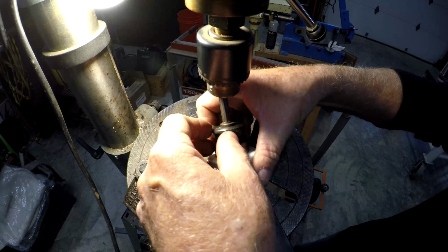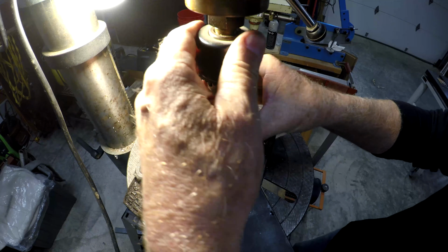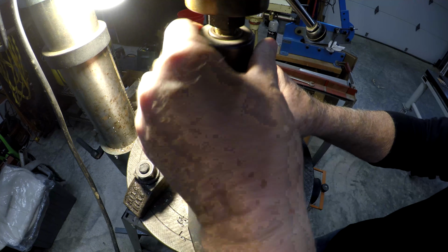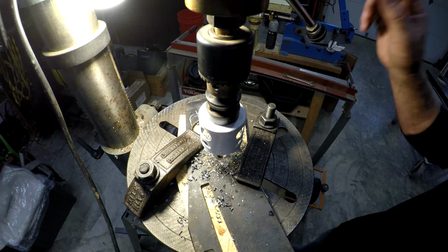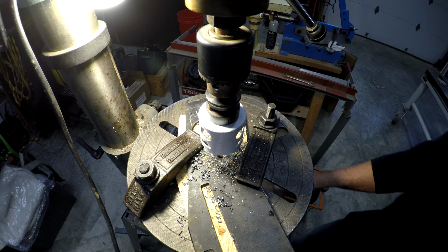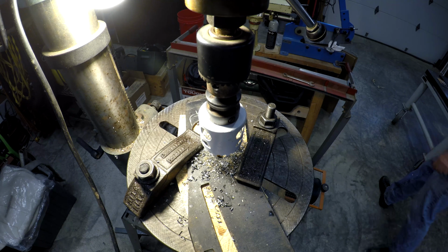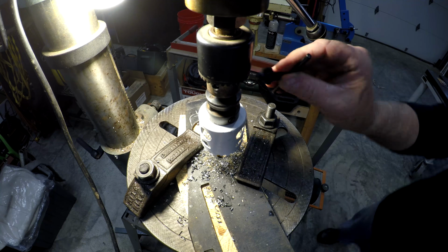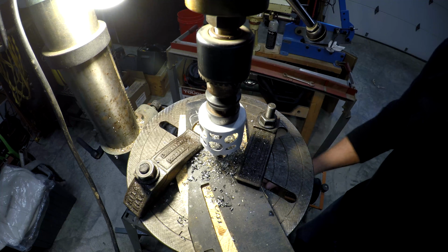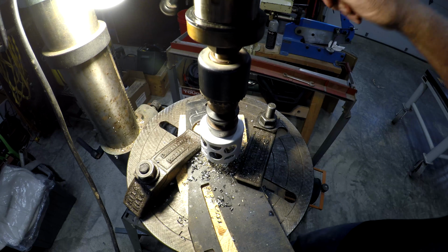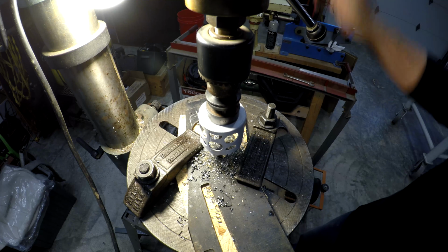Next step is to drill out the disc. So that's going to be a 2 1/8 inch hole saw. So that will give me approximately a 2-inch disc. I don't like drilling with hole saws on the drill press. I'd rather do it on the milling machine. This clamp's good, but the other one's going to move.